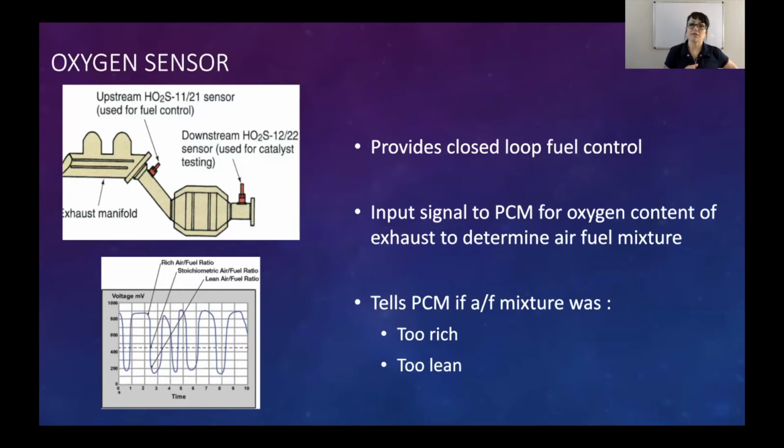And then you have to decide, is that a reading for a bad sensor? If so, I need to check the sensor, not just replace it. Remember, we diagnose things. We don't just change parts. That is what makes us diagnosticians. That's what makes us real technicians that are worth money. If you're just a parts changer, we can teach anybody to do that.